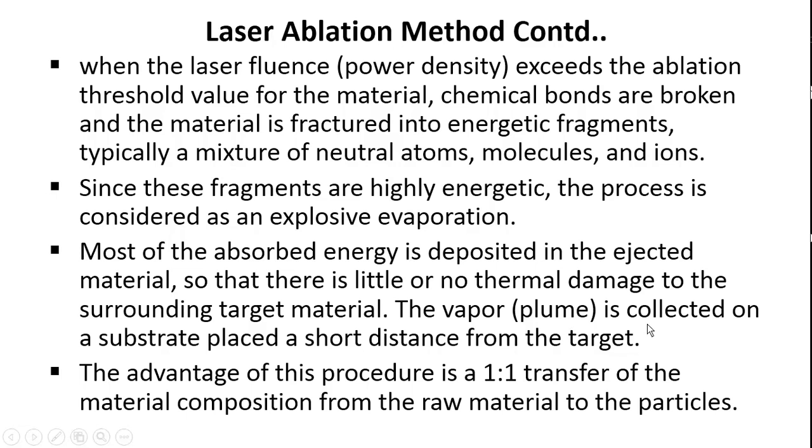The vapor is collected on the substrate, placed a short distance from the target. Actually, this vapor is placed very near to the target level, so this plume can be very easily deposited upon the surface. The advantage of this procedure is a 1:1 transfer of the material composition from the raw material to the particle. That is the main advantage.